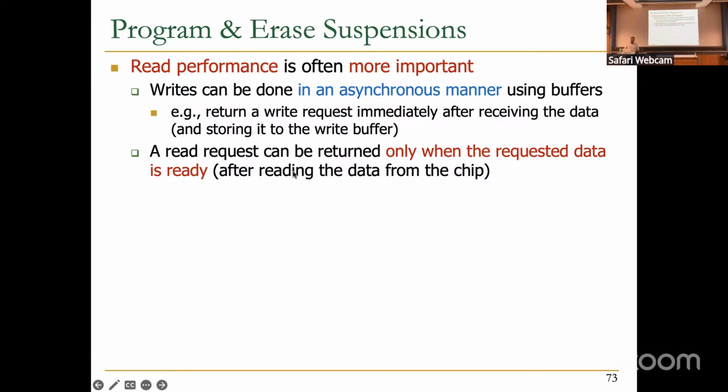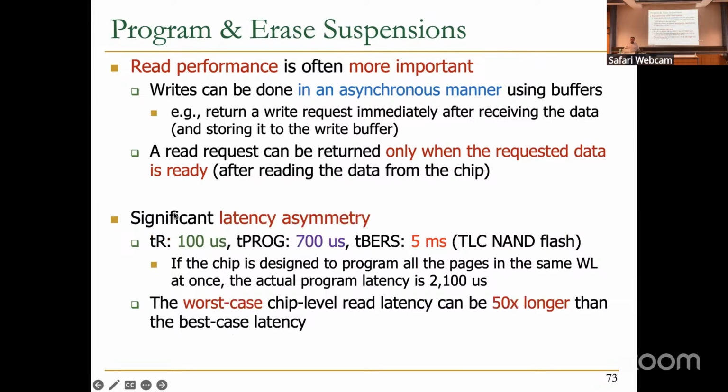However, a read request can be returned only when the requested data is ready after reading the data from the chip. So the problem is that we have significant latency asymmetry here. Read latency is 100 microseconds, but program latency is 700. And erase latency, I said 3 milliseconds, but it's usually around 5 milliseconds for that specific SSD.